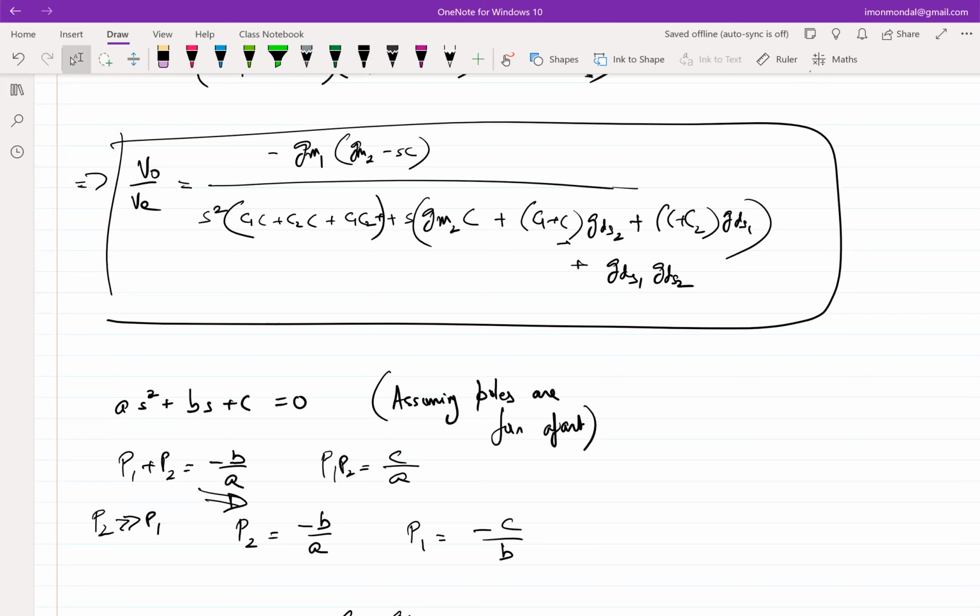We are trying to find the roots under the condition that my two-stage amplifier works properly. For that, the poles have to be far apart. That is a condition that I know needs to happen. So if I am looking for that condition, why don't I impose it directly while finding the roots?